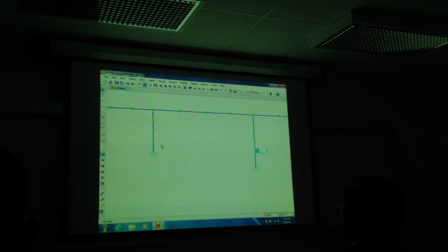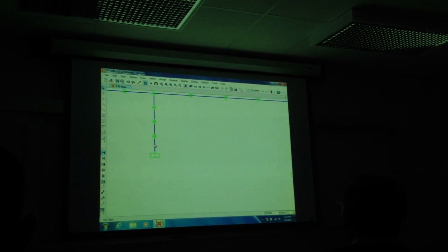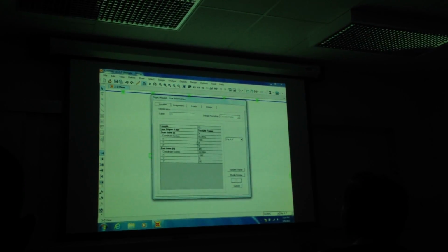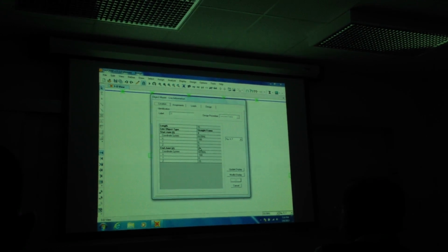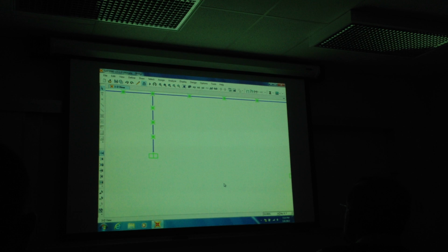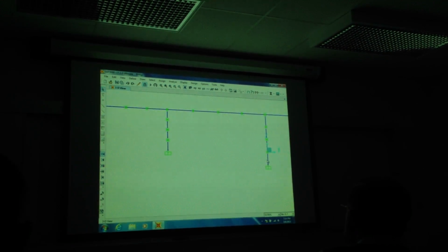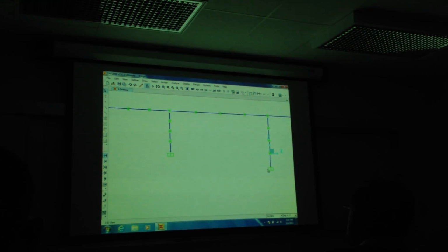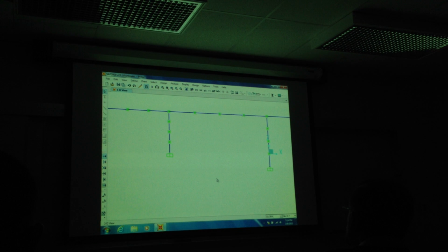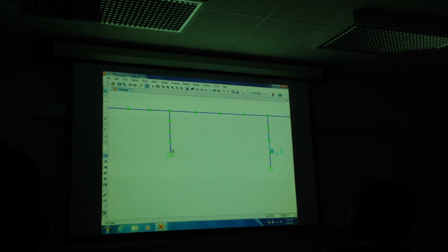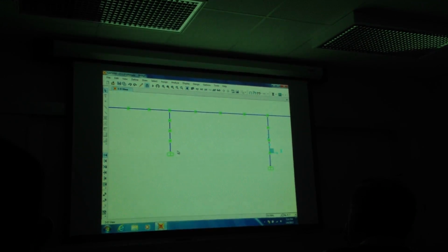Okay. We'll come back and look at these in a few seconds, it's done. I want to go back and look, this is the 26. It's looking at location. It starts at joint, the I is the starting and J is the ending of any member. So it goes from 3 to 23. If we click on here, that's 3. Okay, so 3 is the beginning. And then let's check the other one. It starts at joint 5. So let's make sure it's joint 5. Okay. So what we're doing is we're pulling the moments out at the 0 location at the beginning of the member. If we wanted it at the other end, you'd say 1. It would be at the top or any value.